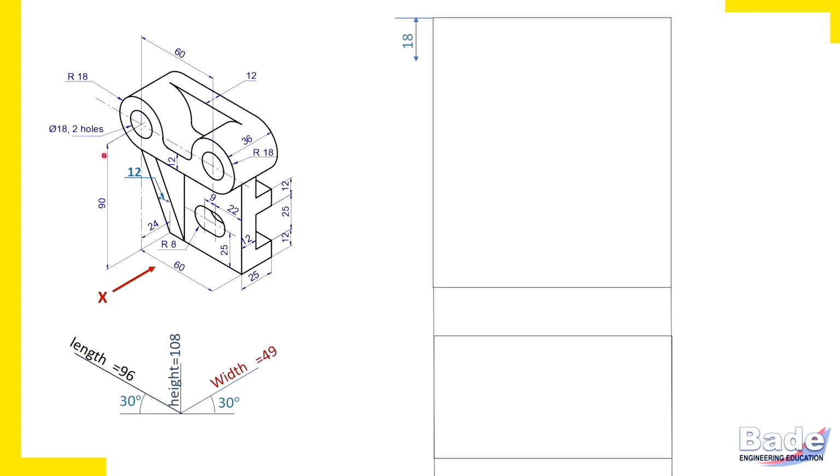These are hollow cylinders. So locate center. From top at distance 18 mm, that is the radius of the object, this center line which is parallel to length. So I am drawing that center line. This center line is parallel to length axis. Length appears horizontal in the front view. So from top, measure 18 mm, that is center is at distance 18 mm from top, and then draw the center line.